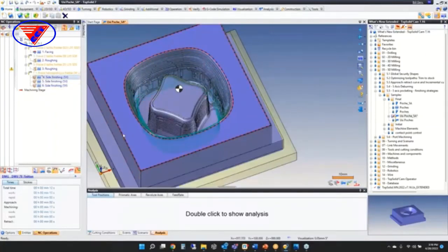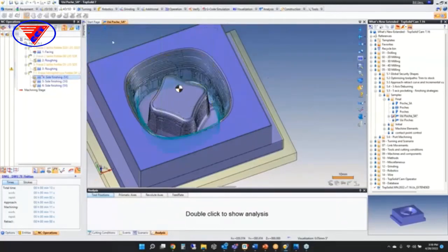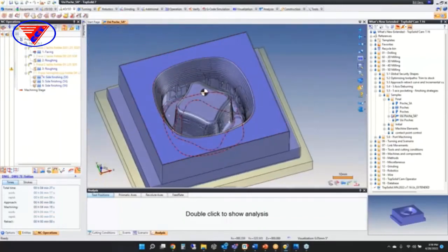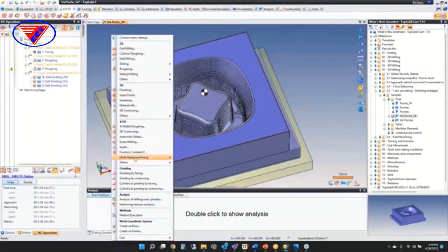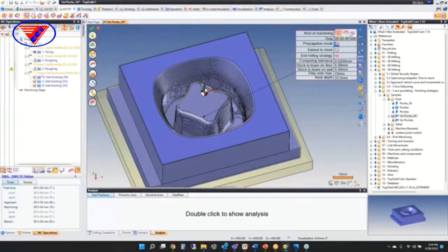So, at the end of the day, multi-axis pocketing can be used to finish or to rough out a part where the pocket is not flat, right? Well, now we're including the ability to do side finishing automatically and then finishing to the floor automatically. In this case, when we're finishing the side walls, we're going to go ahead and try to do this live. So if I go down to other and go down to multi-axis pocketing, let's change over to side finishing, right?